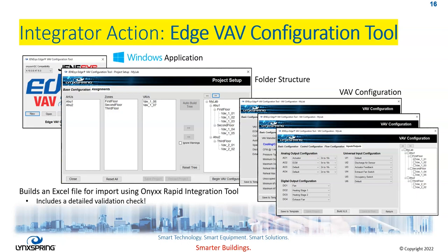You can also use a number for the VAVs and specify that they're to be used for every zone. Doing this enables an ability that allows you to automatically build the navigation tree structure with one click. The naming structure section of the project setup screen is used to customize the names of the AHUs and the VAVs. You can build the navigation structure, which is easy to use in a tree itself, which is actually right here in the project setup folder.